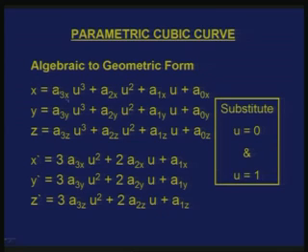Okay. For example, x has 4 unknowns and now I am giving 4 inputs which are related to x. What are those? Starting coordinate of x, end coordinate of x, then starting tangent vector x component and end tangent vector x component. If I substitute that, I can solve this 4 by 4 equation and get a complete representation for x purely in terms of geometric coefficients, not the algebraic coefficients as we discussed earlier.